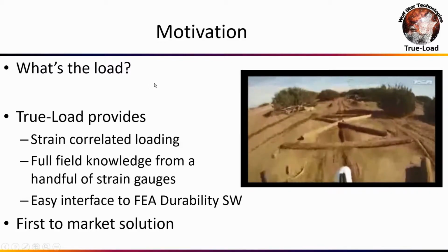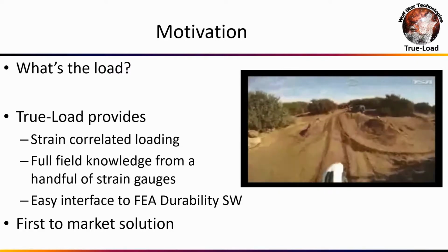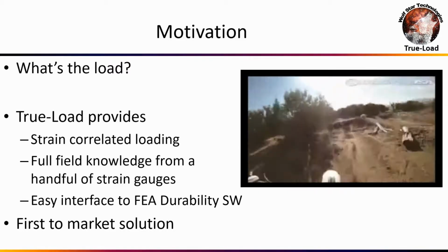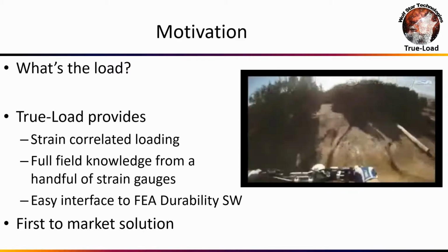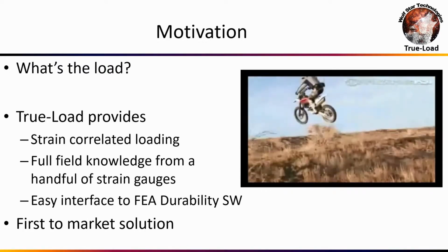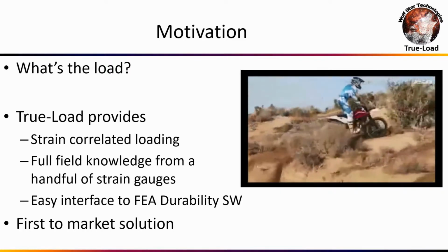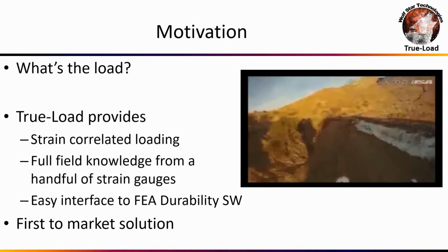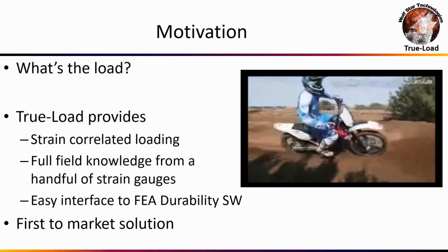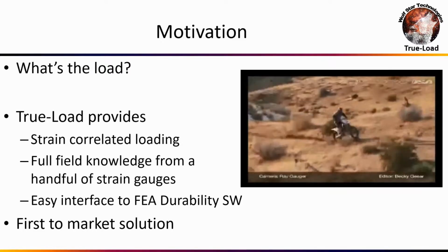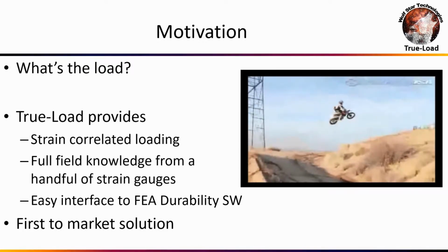This is a first-to-market solution. It's based on a technology called influence coefficients, and that's been around for 40 or 50 years. But the problem with influence coefficients historically is that it's been a very manual, experimentally based technique. Strain gauge placement was guessed at, and setting up the loading in the lab was very expensive to do. And this is all now taking the FEA model and leveraging it through scripting in order to get the proper strain gauge placement and the optimal correlation matrix. So TrueLoad is basically a tool to turn your part into a load transducer.